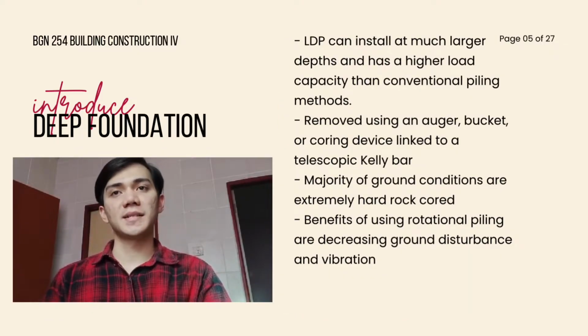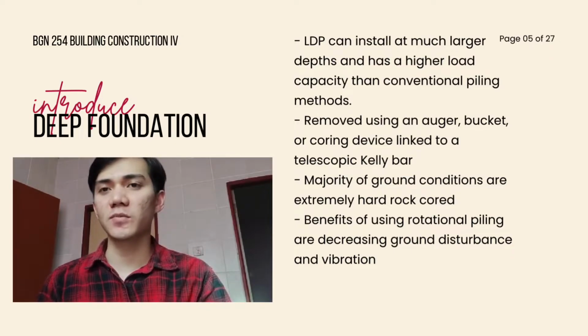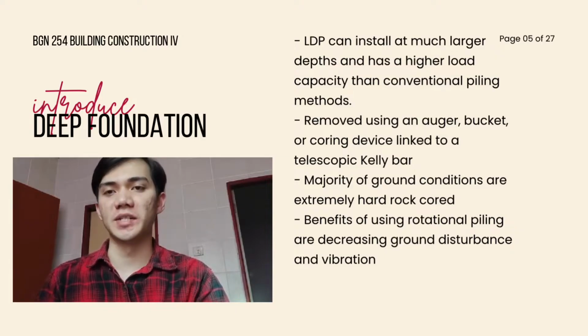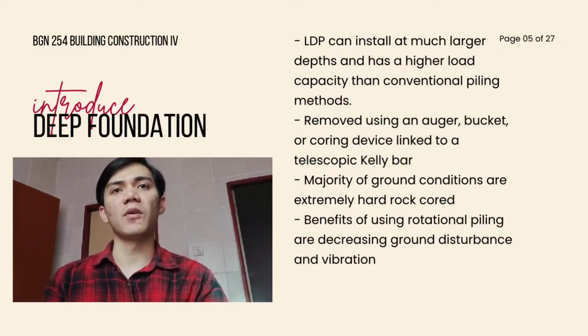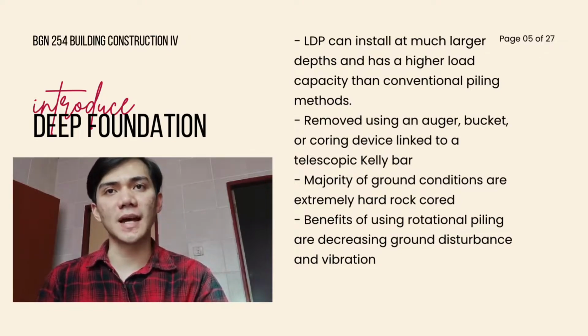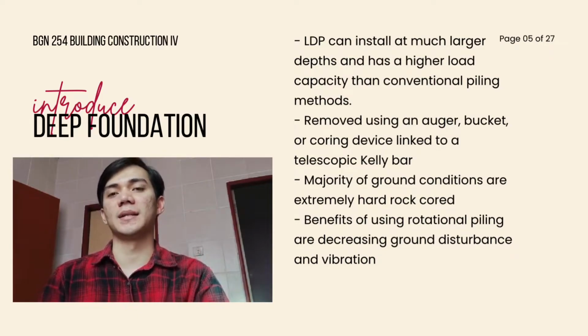Rotary drill rigs in construction offer the ability to modify instruments for cutting or digging and to better suit soil conditions or certain types of auger. It can also include large columns inside the mound to encourage top-down building. LDP can be installed at much larger depths and has a higher load capacity than conventional piling methods.